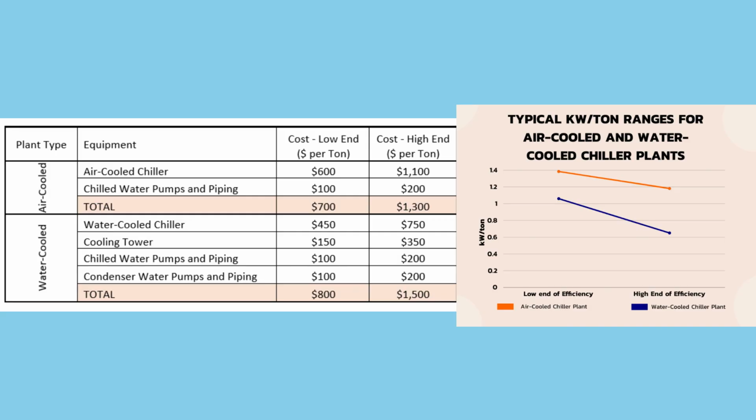Energy and economic analysis. True optimization means looking beyond individual components. Lower chilled water temperature can increase chiller power, but reduce airflow and pump energy. Lower condenser water temperature saves compressor power but can raise tower fan load. Higher delta T design, meaning lower flow, reduces pipe size and pump horsepower.